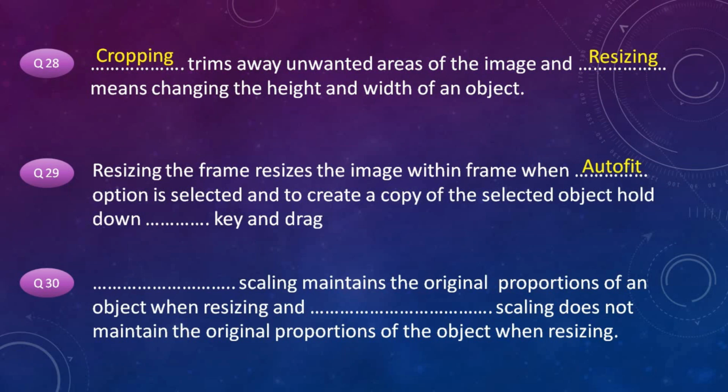And to create a copy of selected object, hold down Alt key and drag. Proportionate scale maintains the original proportions of an object when resizing, and disproportionate scaling does not maintain the original proportion of the object when resizing.